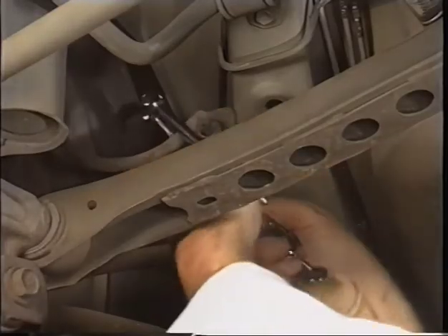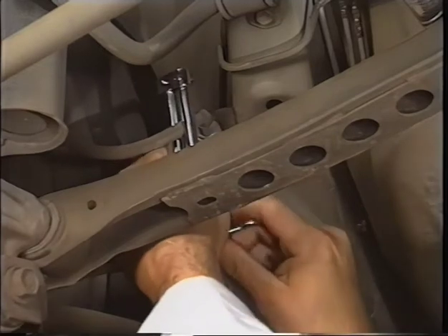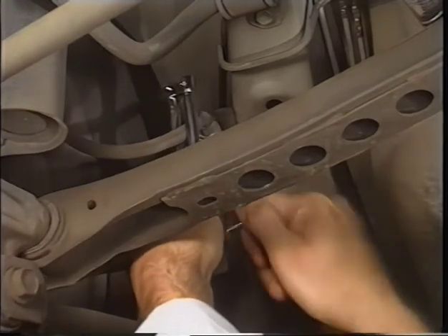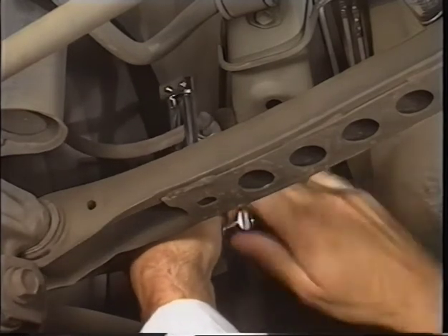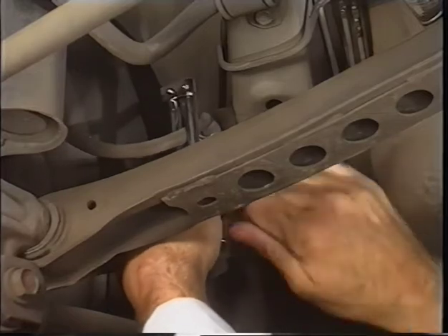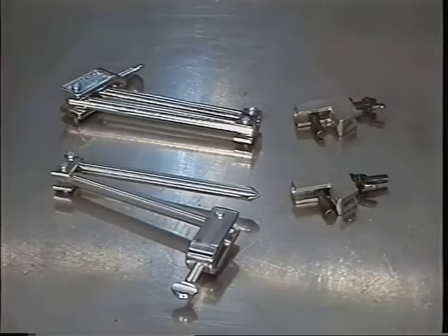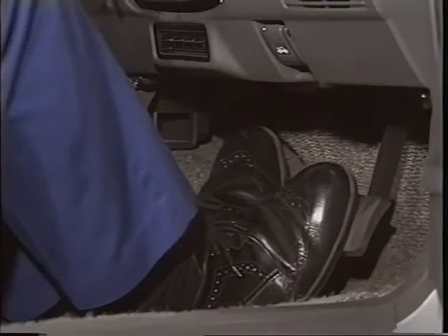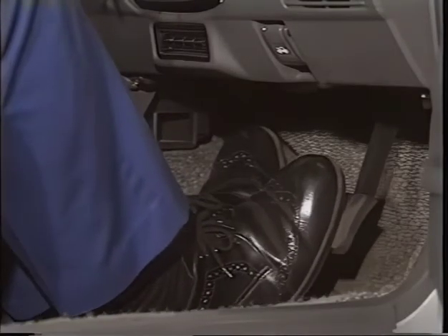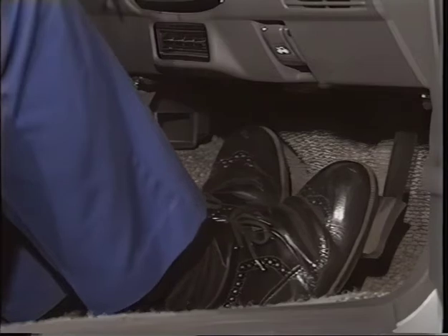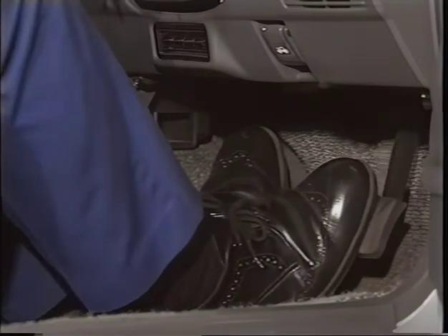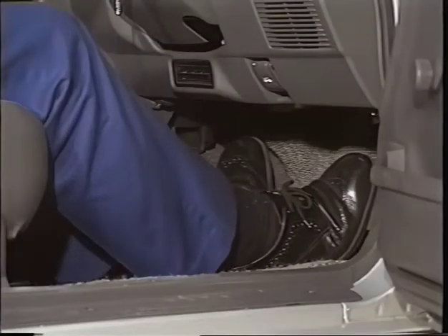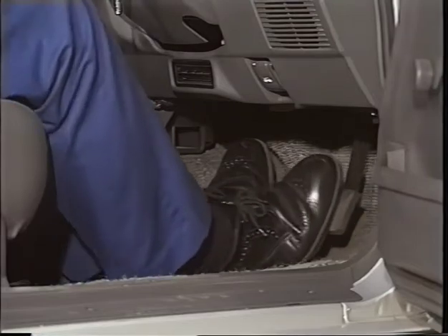If the system passes these initial inspections, the next step is to clamp off all flexible brake lines on the vehicle. This can be done safely and without causing damage to the hoses by using any of the proprietary brake clamps sold by most tool and equipment retailers. The pedal should now be checked for height, and if normal, the fault will lie in the service brakes. If not, the pedal, booster and master cylinder assembly should be checked.